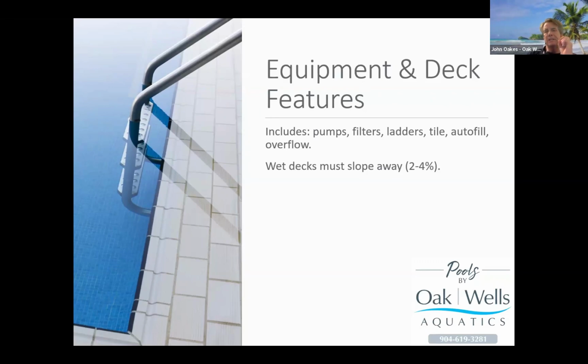Another interesting piece of the pool system that the health department monitors and we have to manage is what they call the wet deck. The wet deck is considered the area of the pool deck from the water's edge 4 feet back away from the water. When I say we have to manage that, it's typically on construction, but this would be pertinent to anyone doing a renovation that includes deck work, maybe a paver overlay on their pool deck.